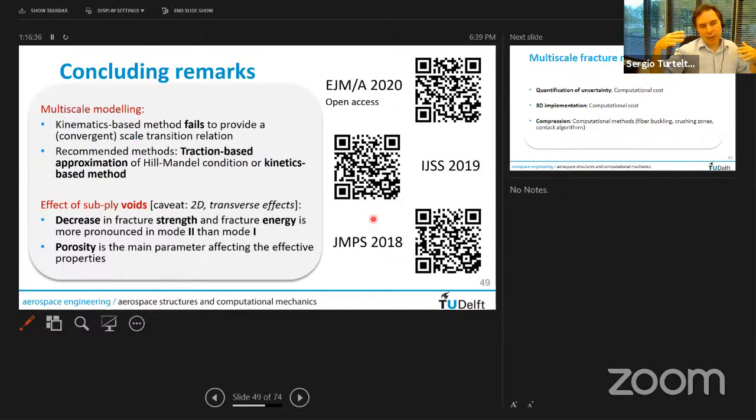Technically, you have to consider an infinite number of possibilities. I could load a material and pull it and then shear it at the same time, or I could change the loading path, all sorts of possibilities, because those would generate distinct types of cracks. You would have transverse cracks, you would have delamination ones, and then all sorts of names for tunneling and you name it. It's distinct fracture mechanisms, and technically there would be an infinite possible number of combinations of all of those. And those cannot be superimposed.